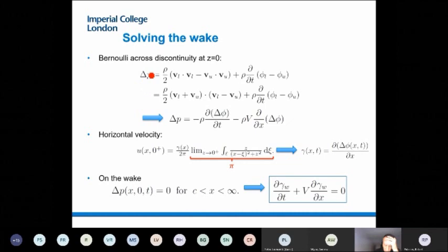So basically what we'll do is to do Bernoulli's equation around the discontinuity that we define in our flow. If I have my previous circle that I brought before, and I have that problem there, as I said. So what I say is I'm defining this boundary condition here between top and bottom. I'm going to define the upper part and the lower part of that discontinuity.